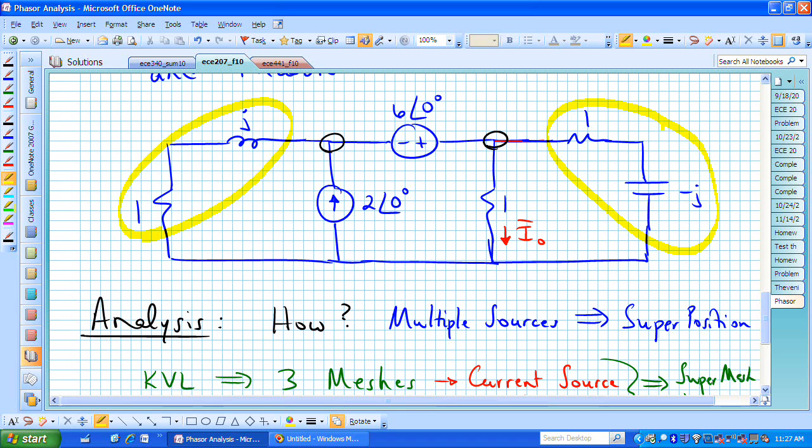The only problem that we might have is the fact that we now have this voltage source in between our two nodes, and we don't know the current that's going to go in that path. But because of that, we can actually simply do a super node and worry about writing our KCL equation with that super node, and then using those node voltages in our constraint equation to relate those node voltages, or to obtain our second equation in the two unknowns.